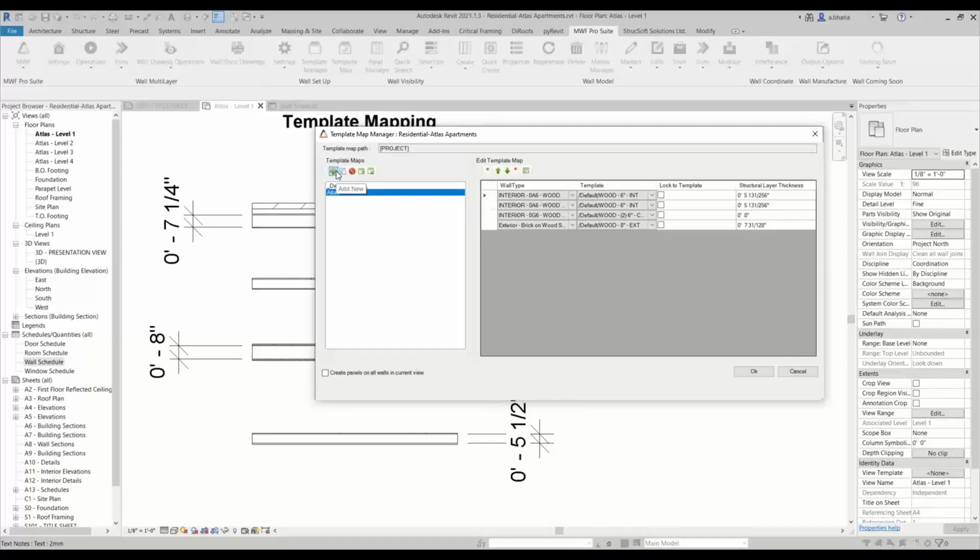So maybe tier 1 might not need extra horizontals or backing, or horizontal studs in the middle of the panel, but maybe your tier 5 or zone 5 wall types might actually require something a lot more sturdy, and it might need different types of framing, basically, right?